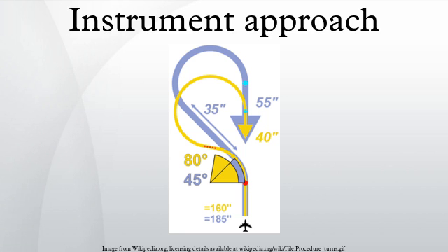According to ICAO Doc 4444, it is enough if the pilot reports that in his/her opinion the weather conditions allow a visual approach to be made. In general, the ATC gives the information about the weather, but it's the pilot who makes a decision if the weather is suitable for landing. Once the pilot has accepted the clearance, he/she assumes responsibility for separation and wake turbulence avoidance and may navigate as necessary to complete the approach visually.